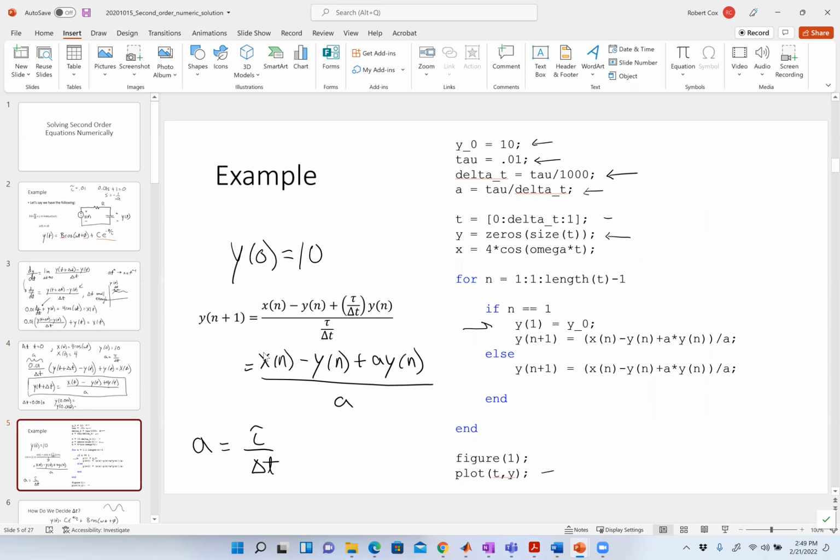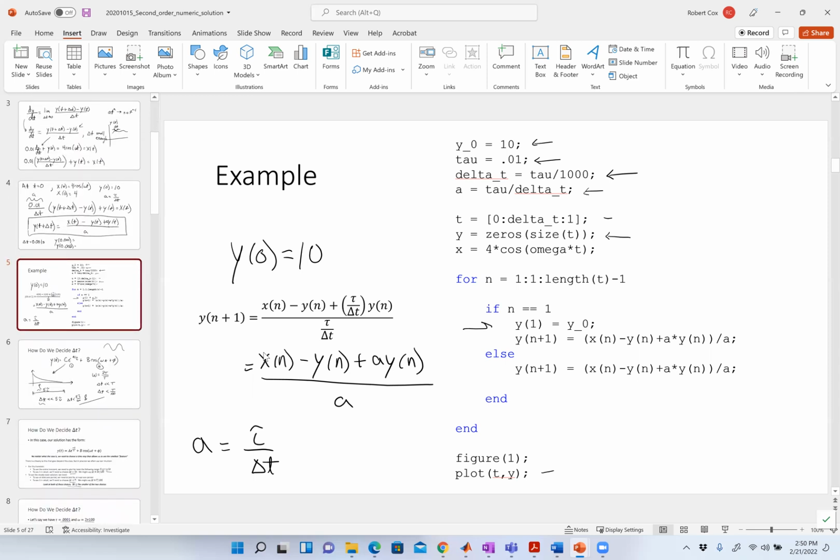What we said last time is here's a piece of code that would do this. We walked through it, and I said I don't necessarily need to have the t values present in my expression. That was one of the takeaways last time. That formula can be reduced to something where the next value in the output depends on the current value in the output and the current value in the input.